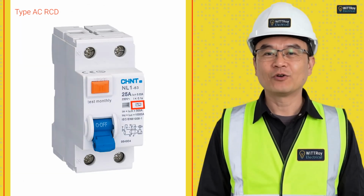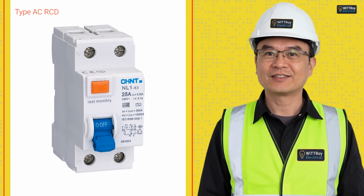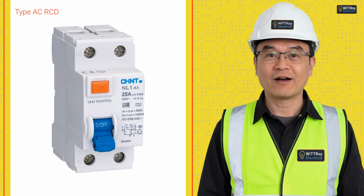Let's look at this device. Now look at the symbols. The symbols can detect AC leakage. This is a 1-phase type AC, 30 milliamp, 230 volt 25 amp RCD.